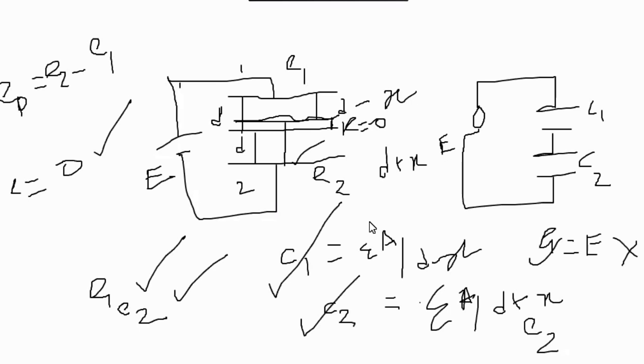From that equation you can establish a relation between the output voltage E0 and the displacement x. After calculating the net output voltage E0 equals E2 minus E1, you can establish the relation between E0 and x, and decide whether it shows a linear response or not.